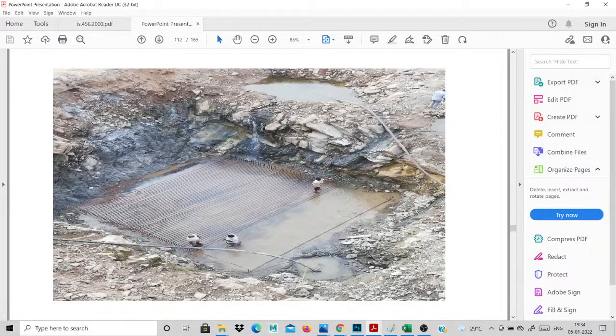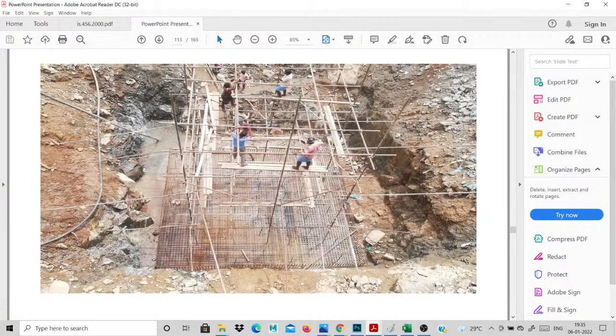First of all, you do a soil test. For any building you design, first of all you go for a soil test. Then you design it. But it's a riverbed area, and the SBC is high. So a normal isolated foundation is chosen. This is our riverbed area. It will be excavated fully in the rock area. Then you give the normal pedestal foundation. See, automatically it will give the pedestal foundation. Then go for normal columns and piers, etc.